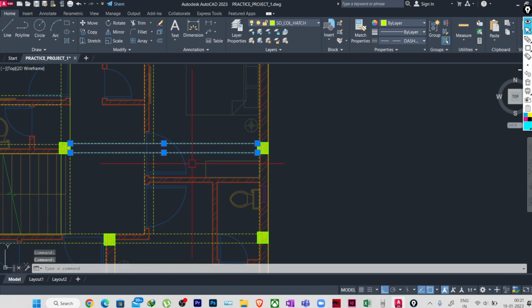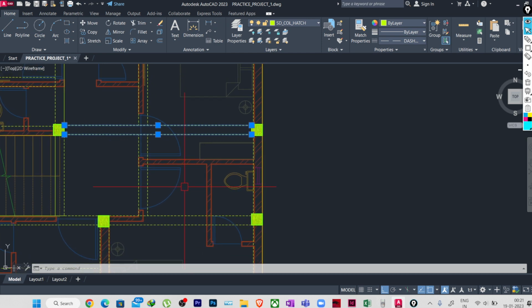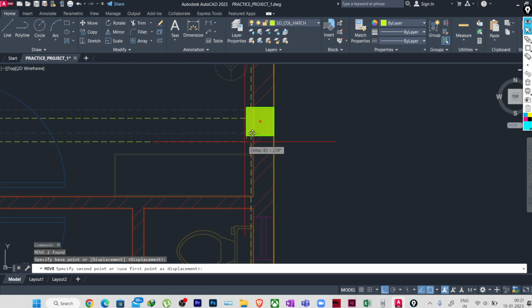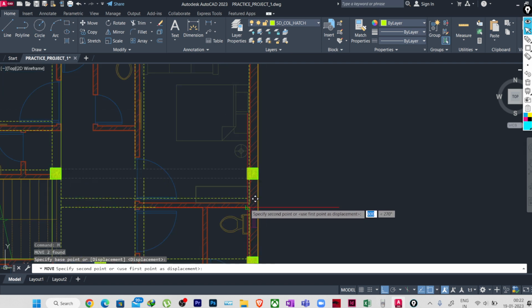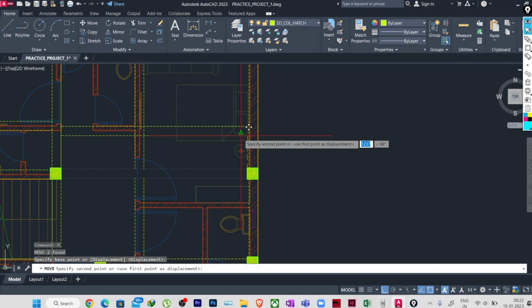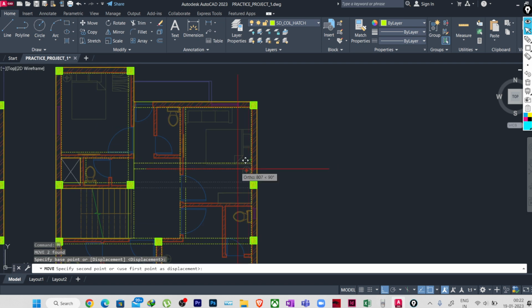This beam, instead of providing here, though we have these columns and it will be easy to place these beams because we have another wall here, so we need to provide some beam here also. Okay, so what I am thinking, if I provide this somewhere here like this, that too is possible, but the panel size will be very high. Okay, and if I provide like this, I think it is a good option. Okay, it is a good option.